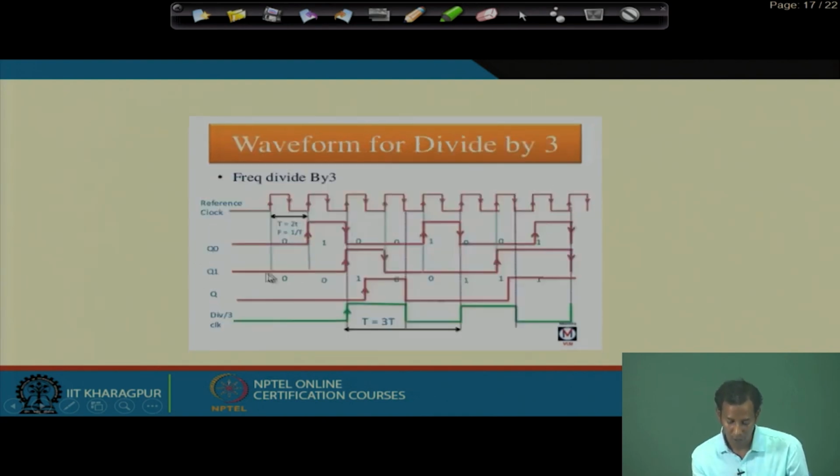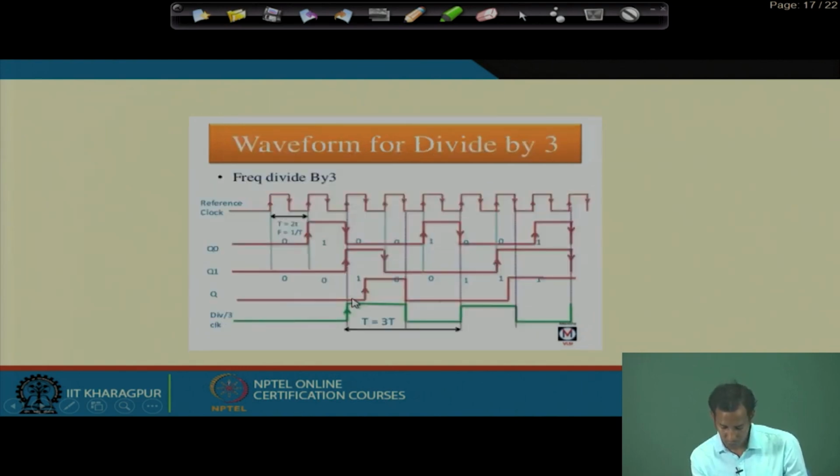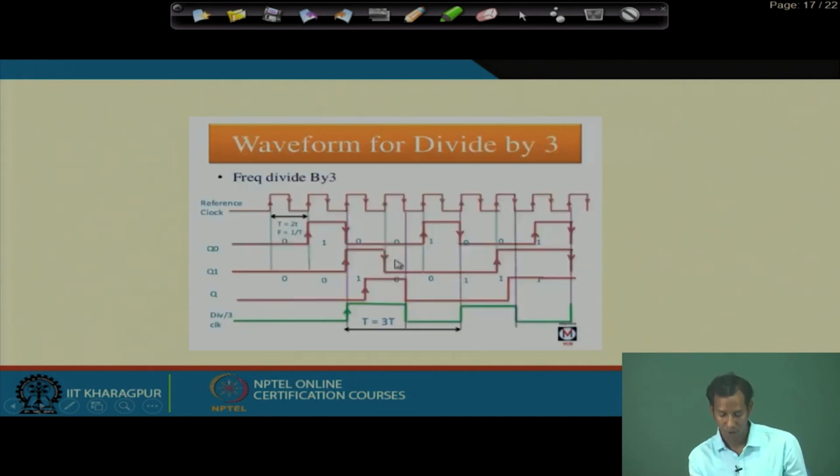Okay. So, now Q1 again is shifted. Q1 is shifted means, depending on the flip flop delay, it will be just after. That means Q1 is now here, and Q is also shifted by the clock to Q delay. Then the output is basically the OR of this Q1 and Q. So, Q is this one and Q1 is this one.